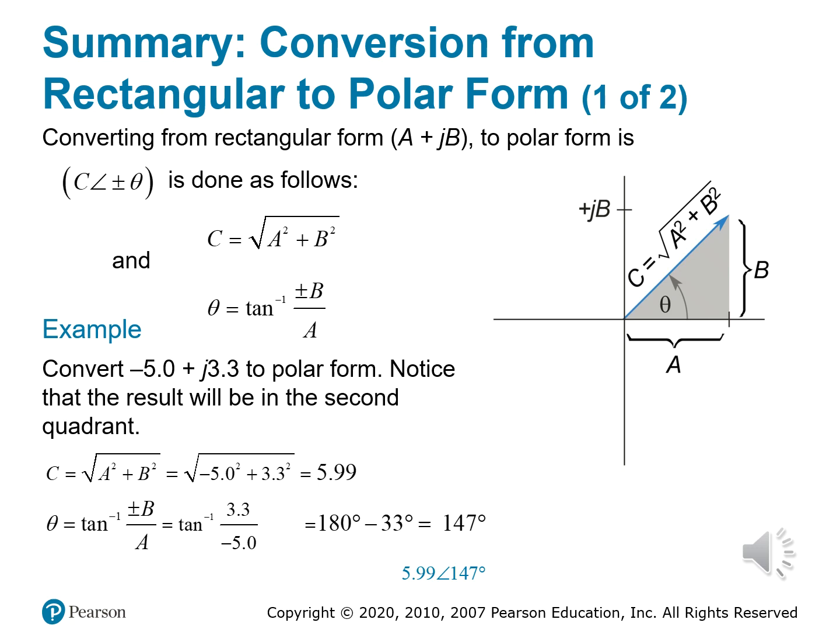A little different between what you may have learned in your mathematics class and your engineering classes, is that we actually put that mathematics to practical use. So here, that math means something direct that you're going to be using. So let's use the polar form when multiplying or dividing phasors, and then the rectangular form when adding or subtracting. Again, multiplying and dividing is when you want to use the polar form, and adding and subtracting is when you want to use the rectangular form.